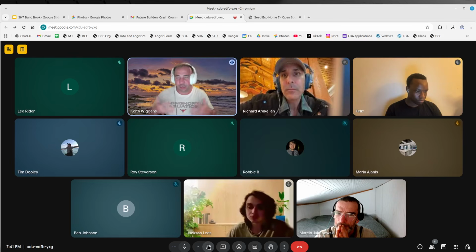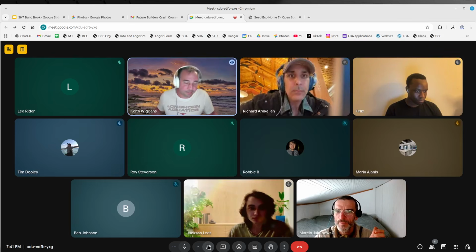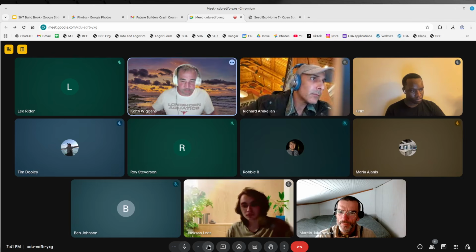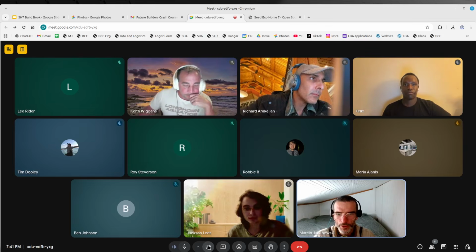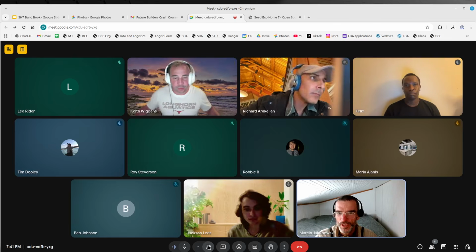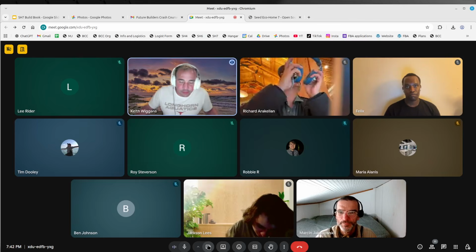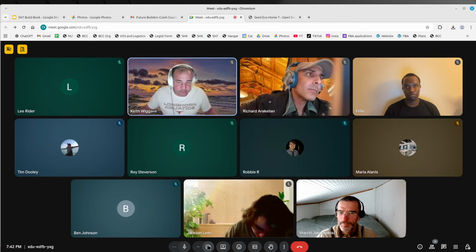If you use a template, it actually looks kind of nice and it's easy to create dimensions on it, a lot easier than trying to use the component and the Draft workbench. Once again, if we organize the file according to specific protocols, you can automate that process fully and spit out the tech drawing for this and so forth. You're seeing that possibility too, Keith? Yeah, it's just that the scale is off. That's all. So I have to figure that part out.